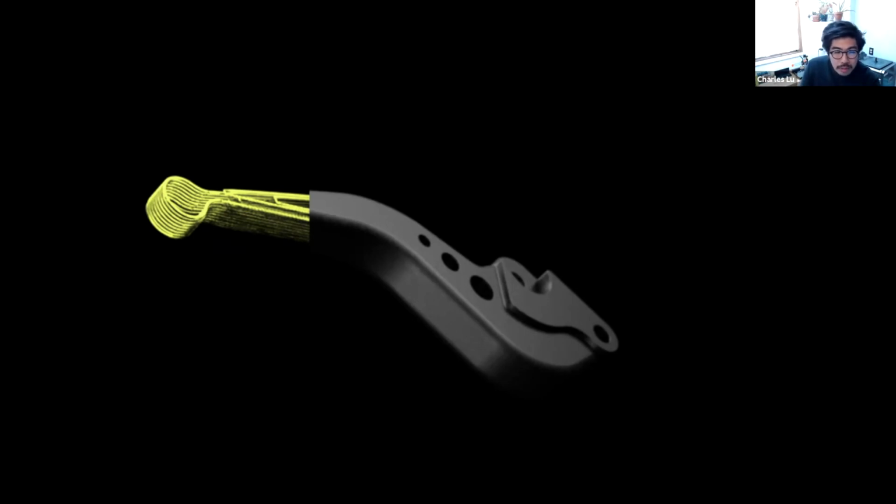Material outdoors, chemical, UV resistance. The nylon based material is already very good outdoors. The carbon fiber, the chopped carbon in the nylon, actually reduces the UV exposure towards the inside of the part. And what that means is that you're going to hold up very well outside. Chemical, not good with acids and bases, but good with solvents. So any sort of petrochemical solvent, it's fine with that. Just acids and bases are nylon's kryptonite.